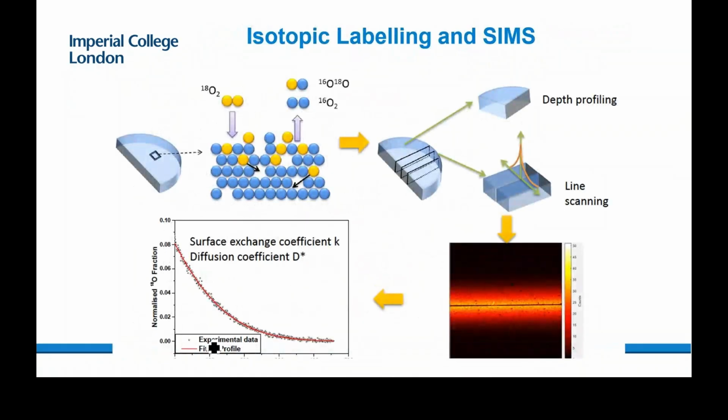And so this is kind of what we're talking about in terms of the SIMS type measurements. So you have this flux across the surface, you take your dense ceramic sample, it has to be dense, otherwise you get your gas species absorbing in the pores, and you then have a diffusion profile from the pore into your bulk and not from your surface, which confuses your measurements.